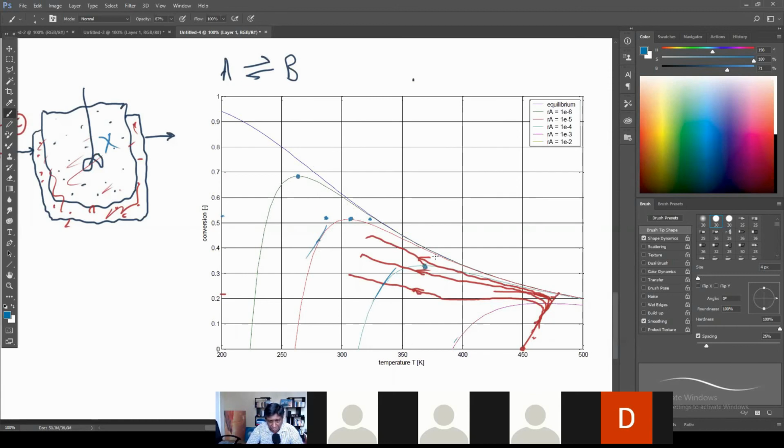So in the batch reactor case, you don't have to draw adiabats and all that. You just go and look at the maximum point on your iso rate lines, and that defines for you the maximum rate line. And that defines also then the trajectory that we want to take.